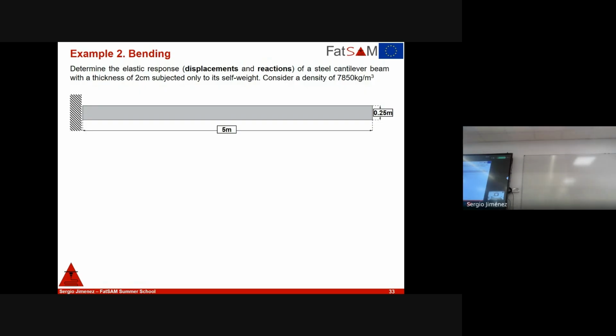This is the minimum value, maximum displacement or minimum displacement in the code. This is the value that should be compared with. Now you should look for the analytical equation to compute the maximum displacement in a cantilever beam, which is subjected to a uniform distributed load, which is basically the same way, and compare the two.